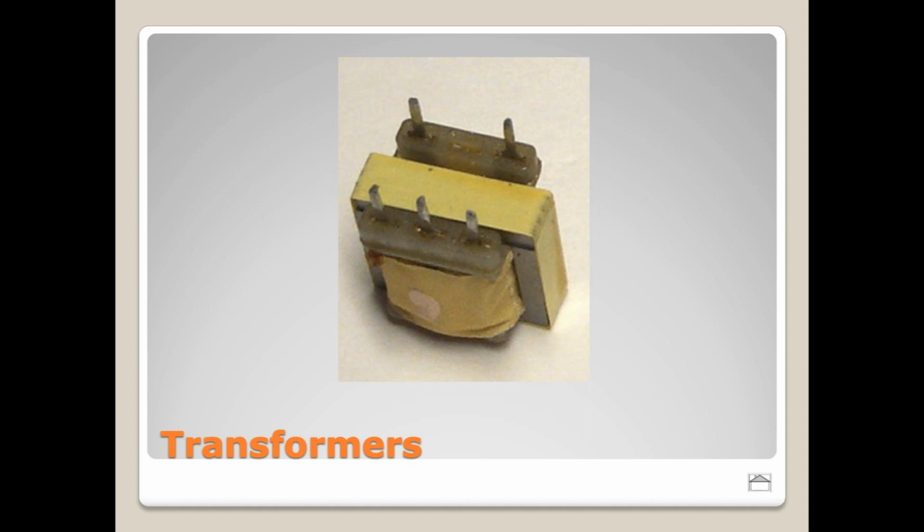So what you see is the coils of wire are inside, and they are actually layered on top of each other. So all the primary and secondary coils are actually sandwiched together in kind of this concentric donut inside. They're, of course, isolated from each other. They have insulation on their own wires. They also typically have paper or plastic, or sometimes some rubber wrapped between the layers to keep them from interacting with each other electrically.